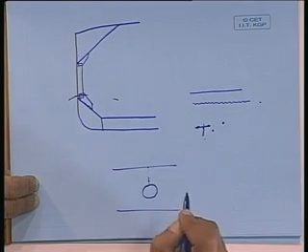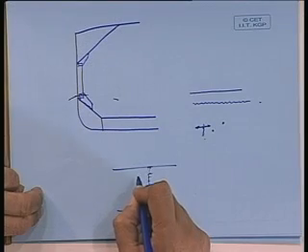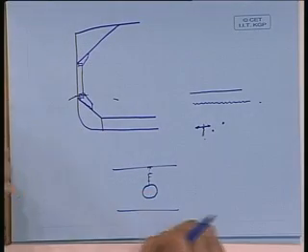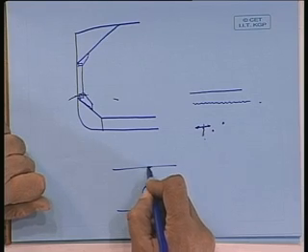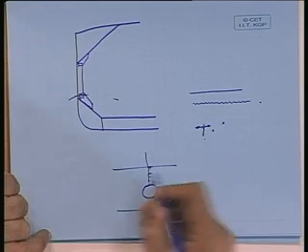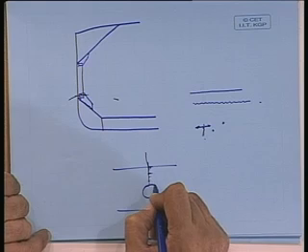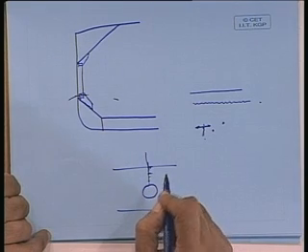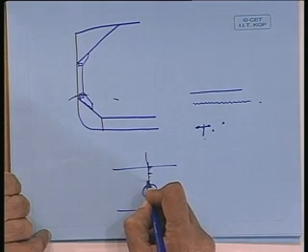After that, when it opens up again, the remaining cross section is less, but still it is capable of sustaining the load. And after that, when it cracks, you find that this is not in a position to take the further load. The stress goes beyond its capacity and the whole thing cracks, and from here to here becomes a catastrophic crack. If you had known that some crack is there, maybe some crack arrestor could have been done and repaired it. But it goes unnoticed in a progressive manner like this.